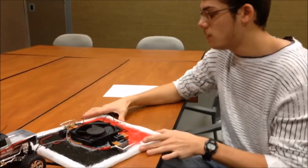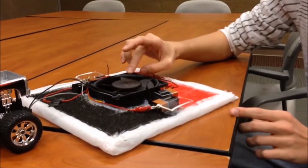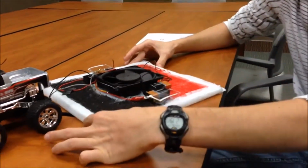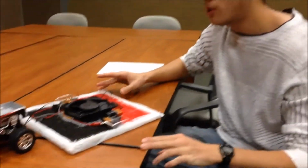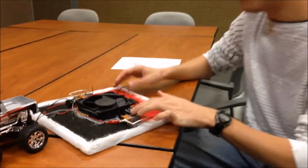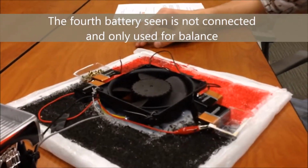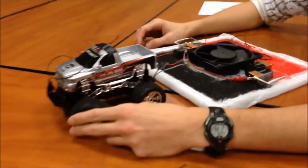The pressure held in by the skirt and the body of the hovercraft, generated by the fan, is what actually lifts the hovercraft. The total amount of force is the surface area under the body of the hovercraft multiplied by the pressure inside. The voltage for our fan comes from these three 9-volt batteries you see here. We're running 27 volts. Up here we have our power for motion.